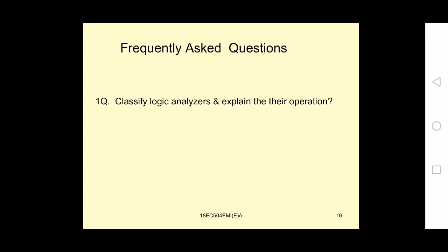And if it asks you to briefly explain the types of logic analyzers, then you have to write what a logic state analyzer and a logic timing analyzer are, which is synchronous, which is asynchronous, in which case how it is used, how the data is stored, and which is used in computer hardware checking or glitches, or in execution of the program. Like that you have to write for 3 marks questions.